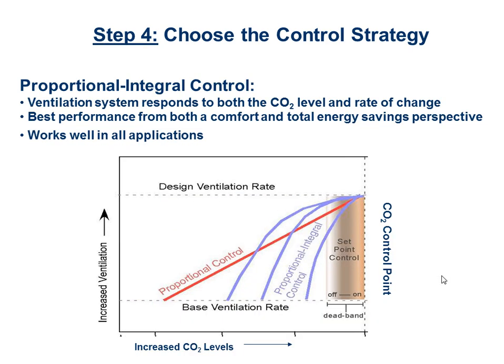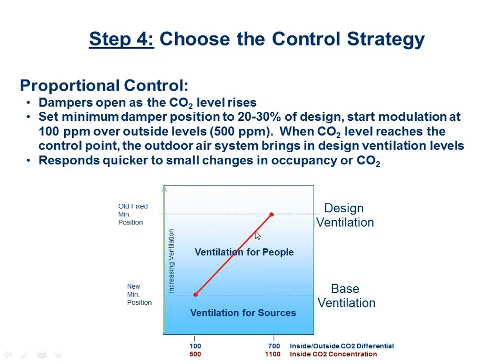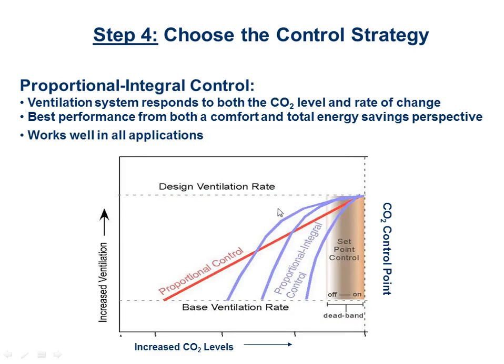And if I want to take it one step further, I can use a PID loop, proportional integral derivative loop, or in this example, just a PI loop, because derivative is too fast of a calculation for HVAC equipment. So instead of having this red straight line like I had here before, this linear proportional line, I will have various curves depending on what's happening at the moment.